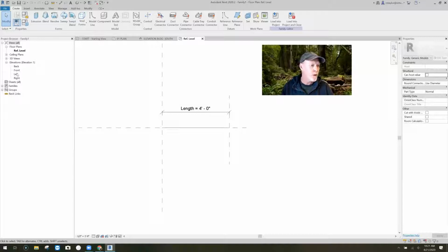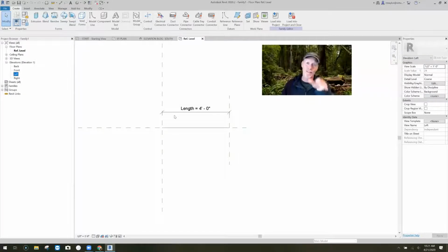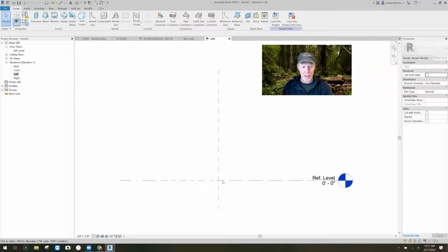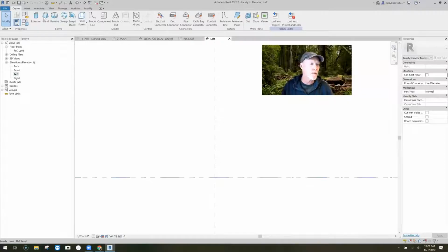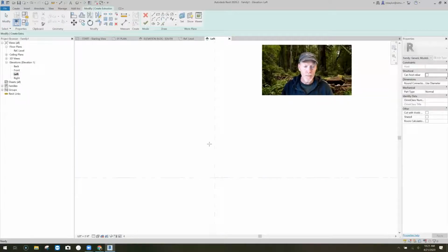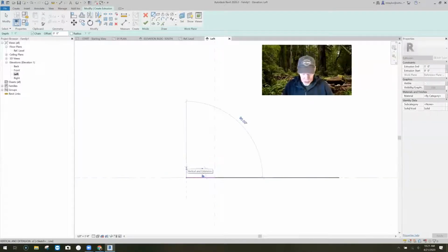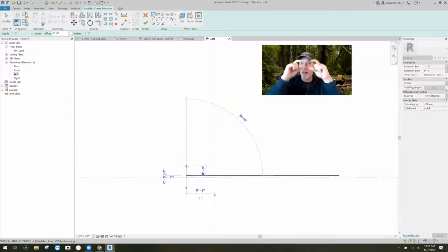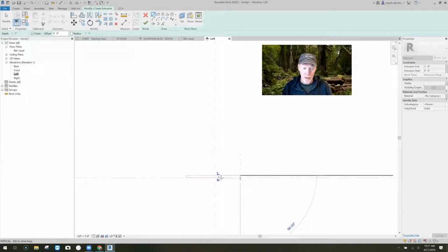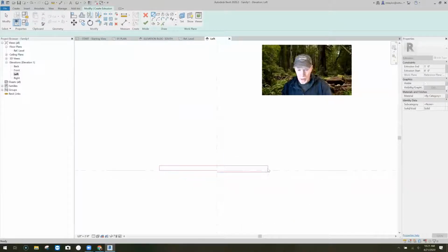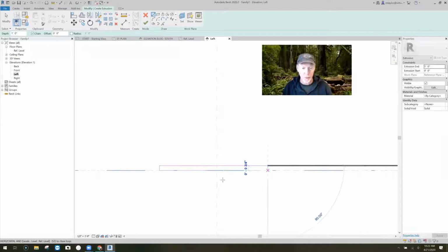So I'm going to go over to my left side. So this is like over on the left side looking at this thing. And I'm going to make an extrusion. Okay. And the extrusion, I'm going to go over any distance I want. I'm going to go up 3/4 of an inch because that's how thick these battens are. And then I head over to the right and down and around. So basically, oops, my bad. I accidentally went too far. You got to actually hit the line and close this thing. There we go. Look at that.